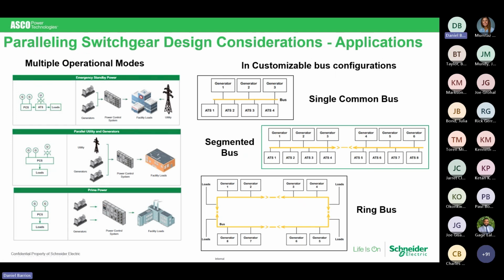Paralleling switchgear design considerations and applications. We've been talking very seriously about a single common bus. We point out something else to you. Most of this gear, if not all the time, we require rear access to make the terminations. When you put it up against the wall, you need to make provisions that we can get back there.